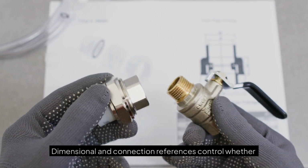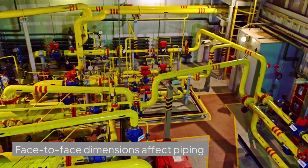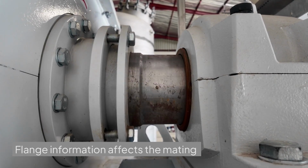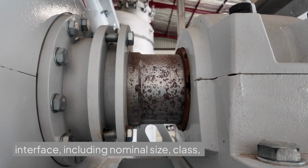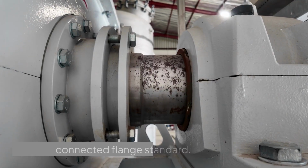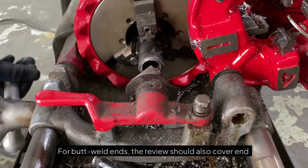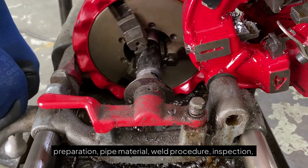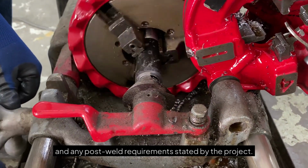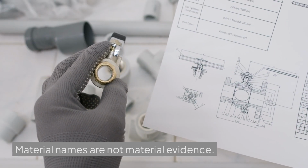Dimensional and connection references control whether the valve can be installed without rework. Face-to-face dimensions affect piping spool design. Flange information affects the mating interface, including nominal size, class, facing, bolt pattern, gasket concept, and connected flange standard. For butt weld ends, the review should also cover end preparation, pipe material, weld procedure, inspection, and any post-weld requirements stated by the project.